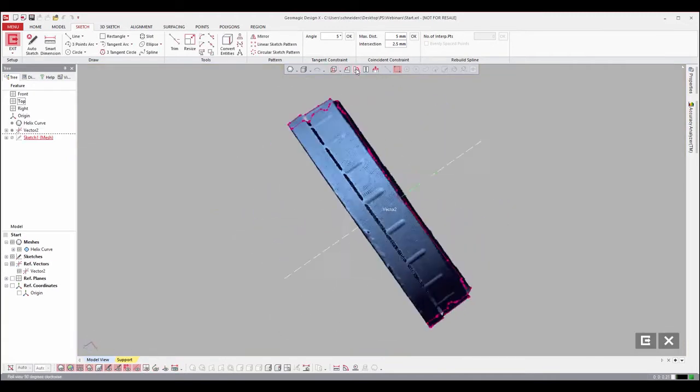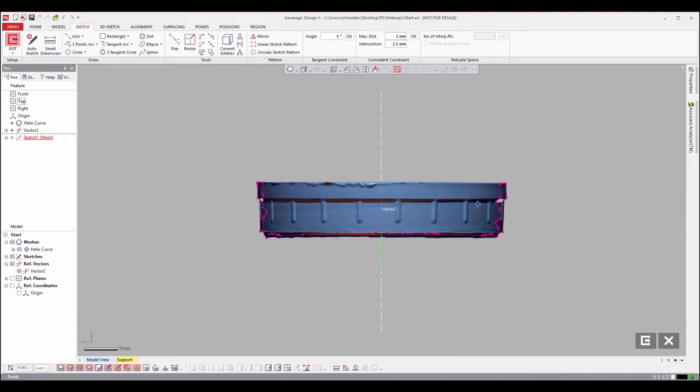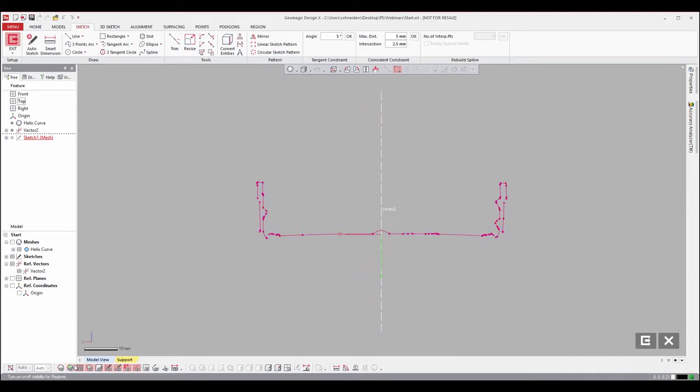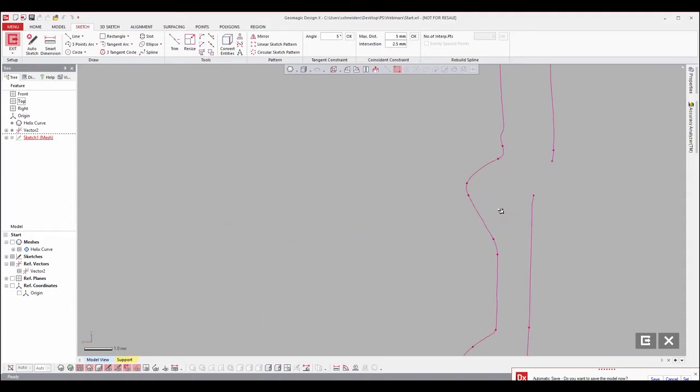We're going to rotate this around and focus on one of these teeth. If we hide our mesh real quick, we can see that our 2D polyline here has two teeth on the right-hand side and then one tooth on the left-hand side. We're going to focus on this top right-hand tooth, because we're going to take this profile and use it in our Helix sketch to revolve it around and create our thread.